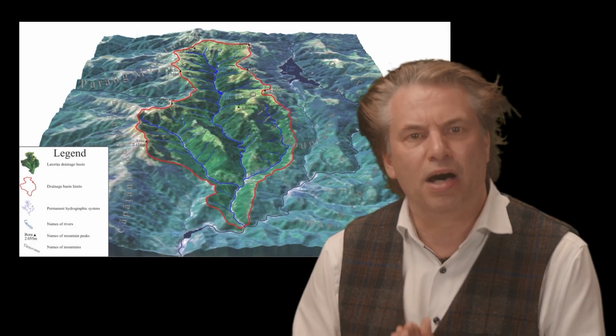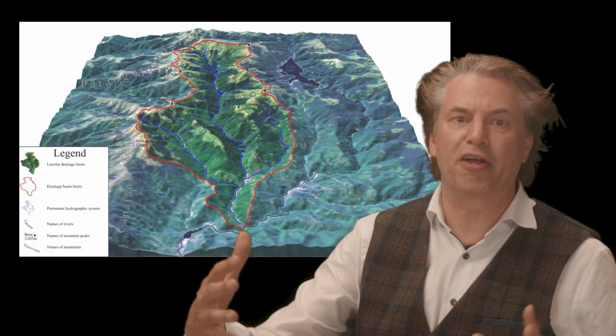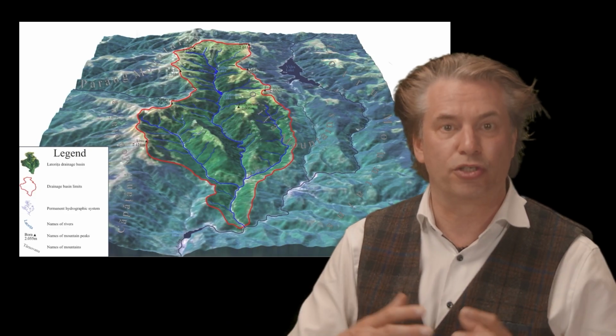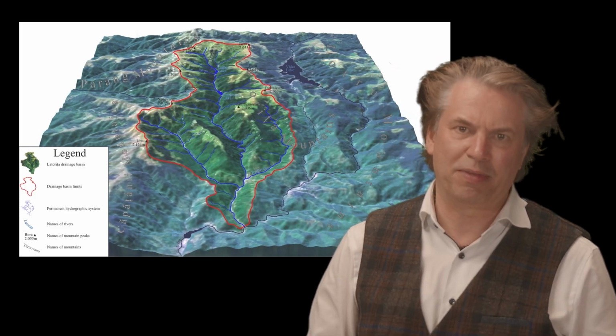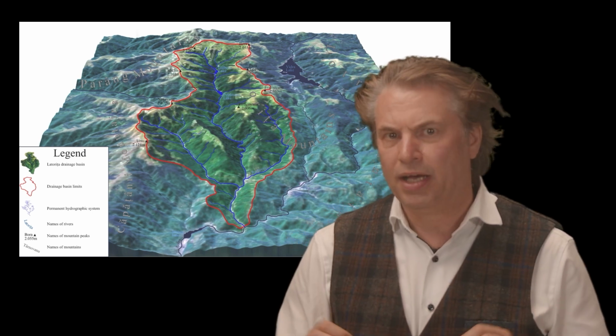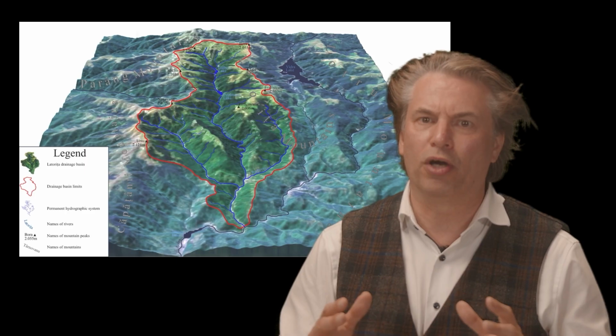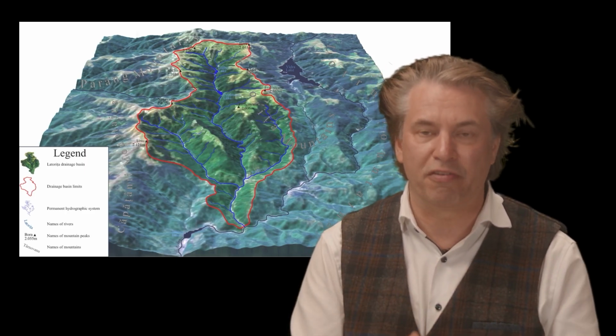The total mass available is strongly related to the amount of rainfall and the total area from which the reservoir collects the water. This is referred to as the catchment area, here enclosed by the red line in this example. This is the total area where the water, typically from rain or snow, collects and drains downhill into rivers and lakes.